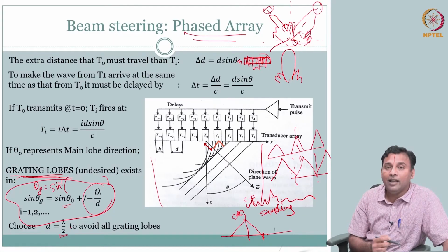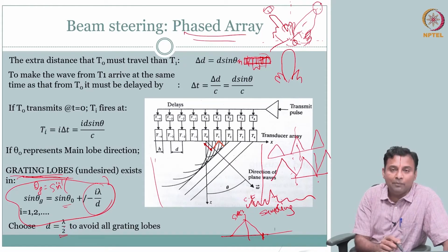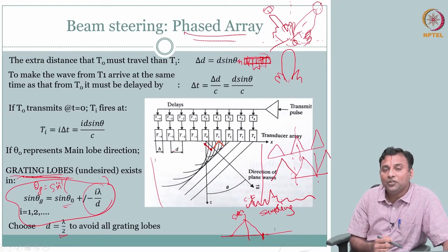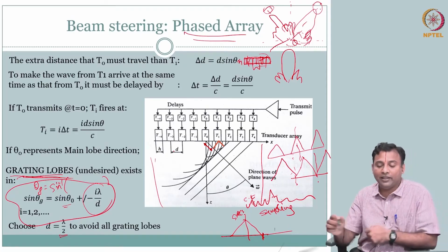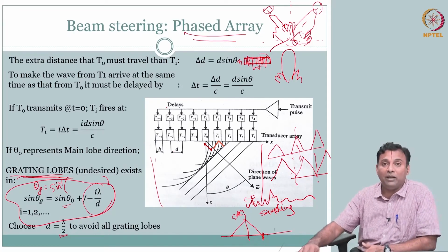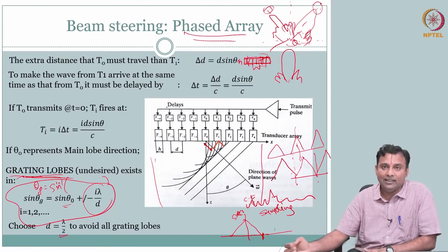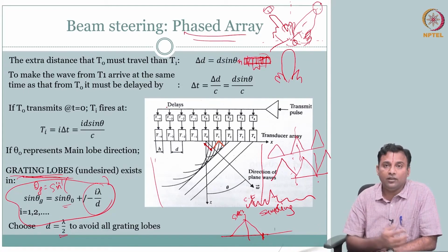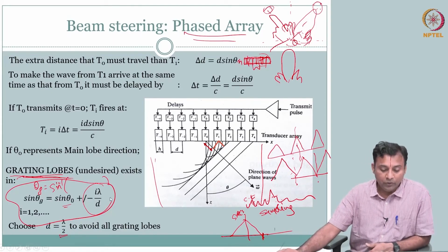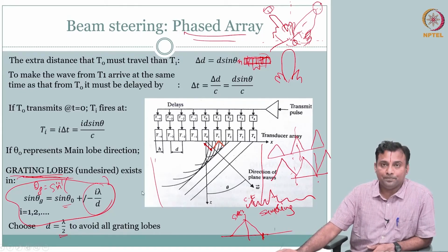Now you see the problem. The higher the frequency, the better the resolution, and the lower the lambda. So, you need to have spacing of lambda by 2. So, you see the intricacy if you are having a high frequency, highly sampled aperture. Then you have to have the corresponding electronics so that each element can do this. So, it quickly becomes very sophisticated. Nevertheless, this is in vogue, this is very popular. It has certain applications where you need to have no grating lobe, clear.